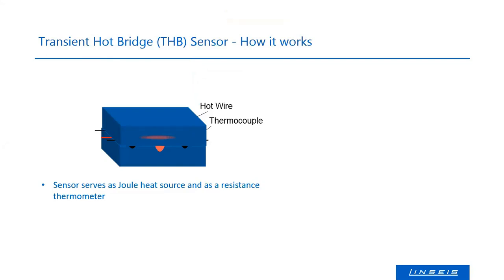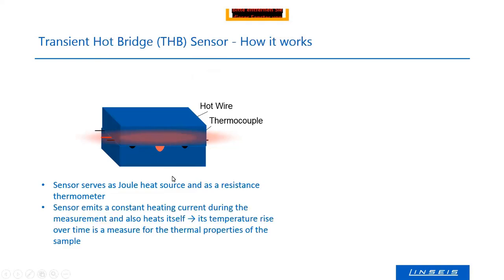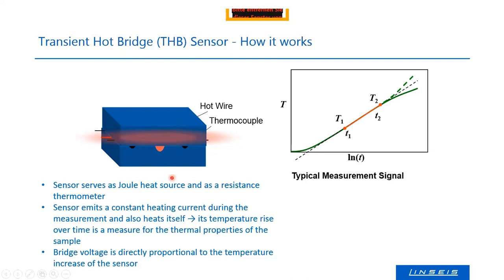And when you start the measurement, the heat is transported away into the surrounding sample, and the measurement looks like this. At the end, we measure the temperature increase on the sensor surface as a function of time. And this temperature increase is exponential.